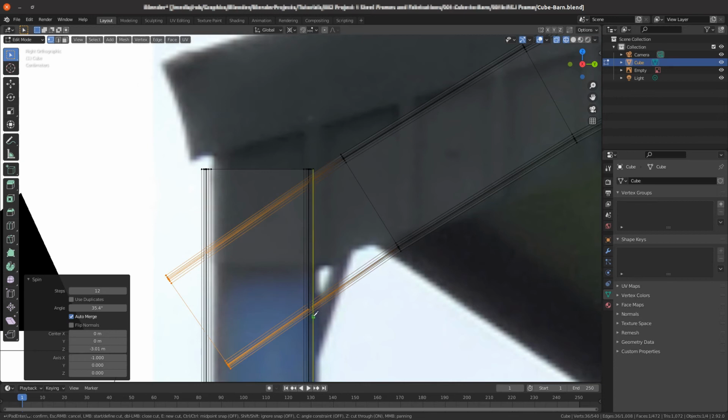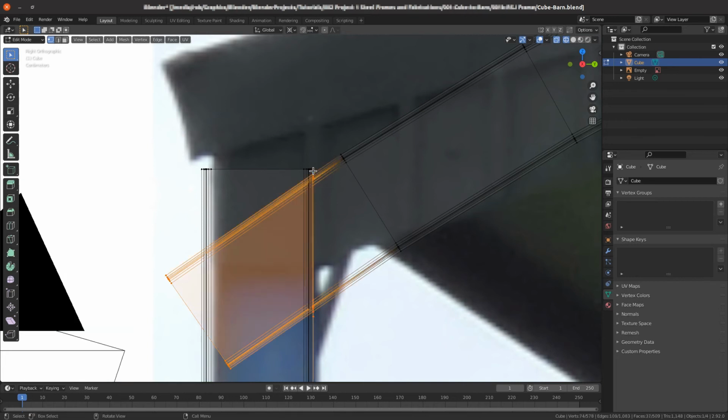We can then go to the outside, or what will be the inside edge of the vertical RSJ, and it snaps to that. If you then click at that point and drag it vertically, you can see it putting markers on all the other points, and again we'll snap to the vertical RSJ on the same edge above the curved RSJ and click again, and it's put red markers now to say that those are the lines that will be cut. So you just press enter and it cuts them.